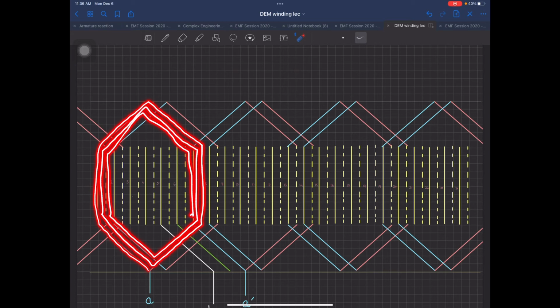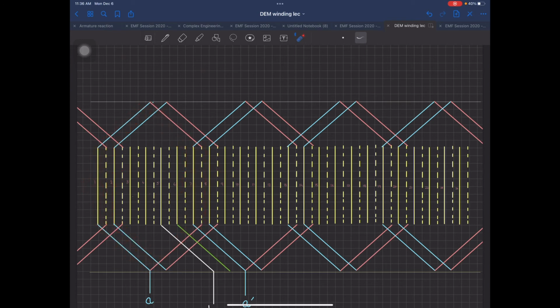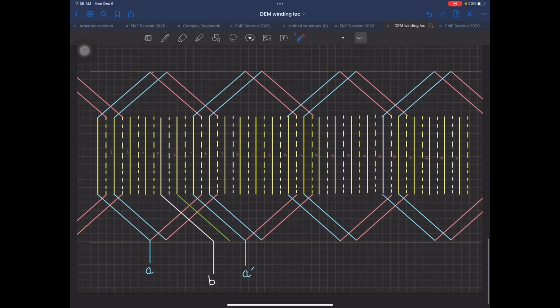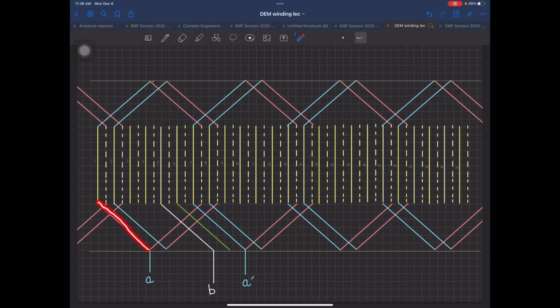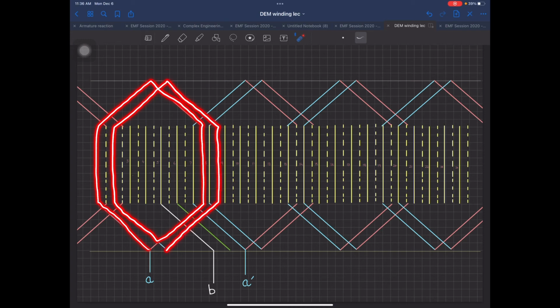ठीक है, जो आप लोगों ने स्टेटर निकाला था, उसके लिए this will tell you how many number of turns you are doing. ठीक है, since this is a double layer, you will double it. Whatever number of turns you do in one slot, you do the second time as well. Now, if you see over here, if I start from the first slot and end at 7, my next winding starts at 2, and then the next coil ends at 8. Now, when I am at this point, can you tell me where I will go from here?